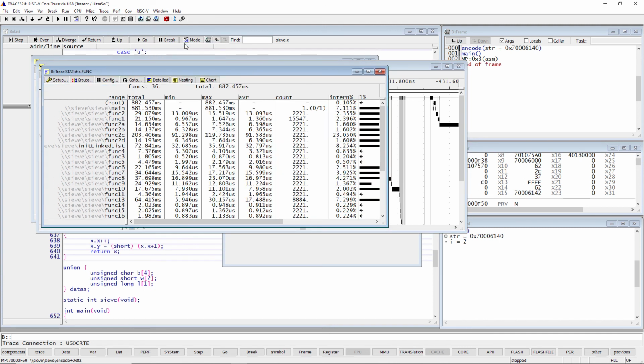This solution additionally supports trace filters that allow to reduce the generation of trace messages. For example, by limiting the generation of trace data for a specific function or operating system task.